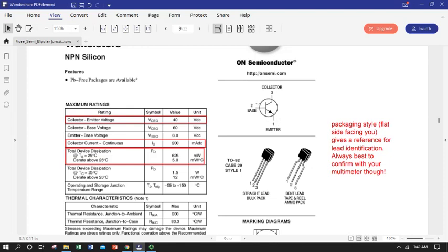So just remember, you've got two PN junctions, one between the base and the collector and one between the base and the emitter, and you can always confirm what you're seeing in these diagrams by using your ohm meter and seeing which one will conduct and in which direction. So that's where you're going to remember that from the standpoint of lead identification, you can view those two PN junctions like two little diodes. So I'll leave that up to you to think about what signal from your ohm meter you would get to confirm the leads, and how you might write up a procedure to do that if you had an unknown package and maybe didn't have a spec sheet available. That's something you should be able to do, a really useful skill.